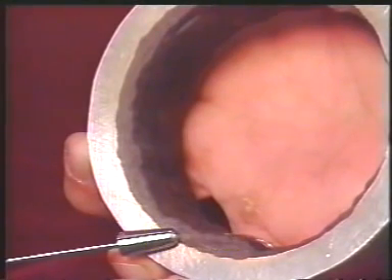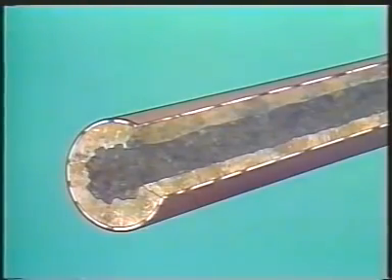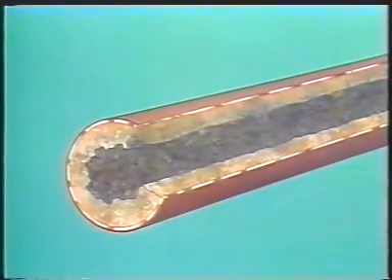Another common furnace problem is the buildup of coke in the tubes. A certain amount of coking occurs naturally due to the presence of carbon particles in the process flow. High temperatures, however, aggravate the problem by increasing the amount of carbon deposits. The coke acts as an insulator, so less heat is transferred to the process flow and more heat accumulates in the metal tube. If the coking is severe, the tube may eventually rupture due to the excessive temperatures.